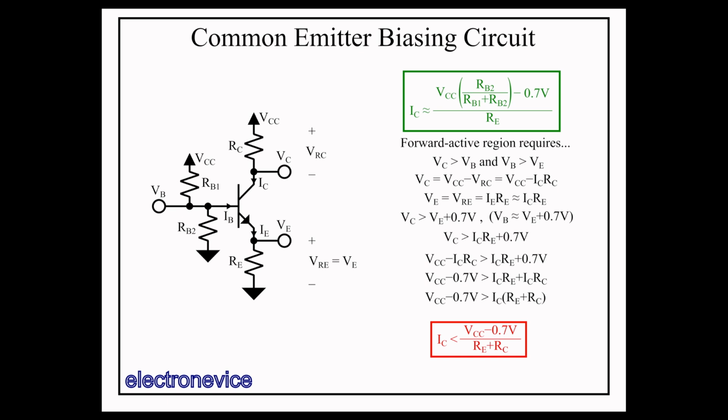So long as this equation is satisfied and the collector current is not set too low, then the transistor will remain in the forward active region.